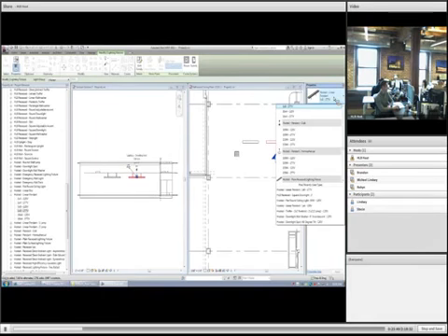So is there any way that, my thought is it might be better for us to copy all of the architect's ceilings and lock them to their ceiling. So we copy a bathroom ceiling and lock it to the bathroom, we copy a corridor and put it on the corridor. Correct. So then we would know if they move the corridor, our stuff moves. You're right. We probably want to think of it in those terms.